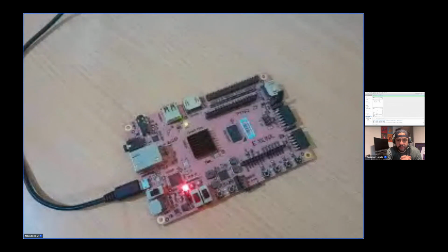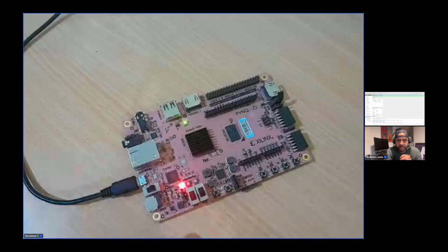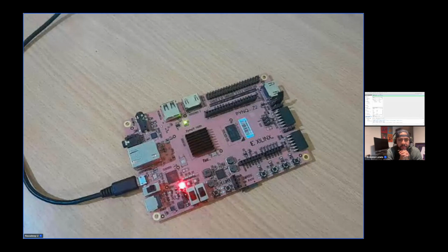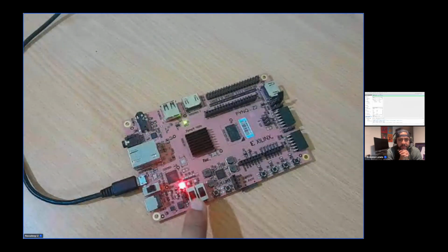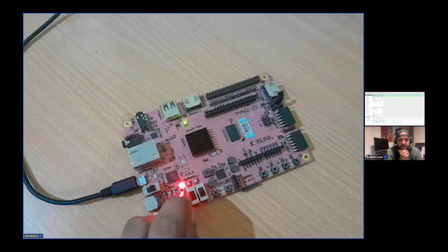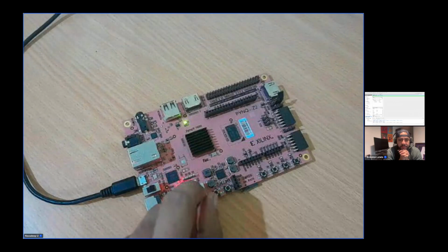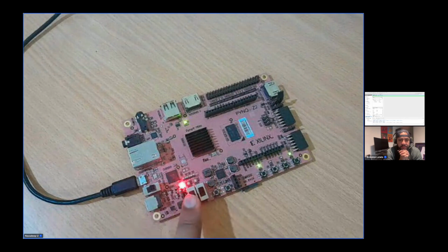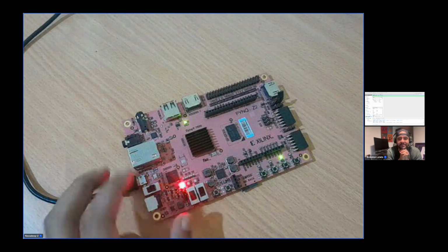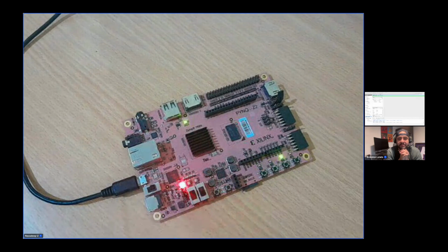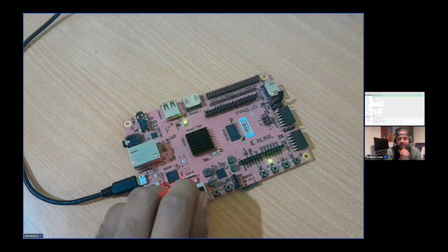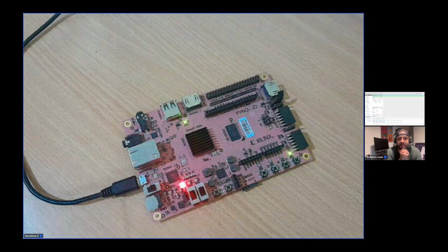Device. So the default state, currently the initial starting state, is S0, which is all the LEDs off, and which is kind of evident from looking at these switches. So now I'm selecting a 0-1 logic, which is the state 1. We should be seeing the LED trail moving from left to right, and then the 1-0 with the LED trail moving to the opposite side, and the final state 1-1, which is just a single LED on.